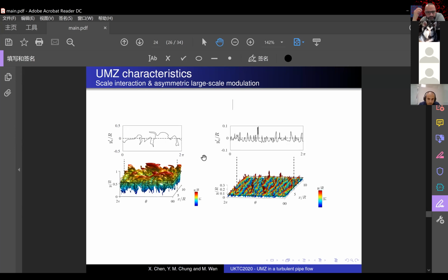And now if we look at another interface from the same snapshot but defined at a lower velocity threshold, being much closer to the wall, we can see a clear bias towards high ejections and bursting events. And also the shape of the ejections and the sweepings are reversed, so the ejections become very pointy and spiky compared to the flattened sweeping structures.